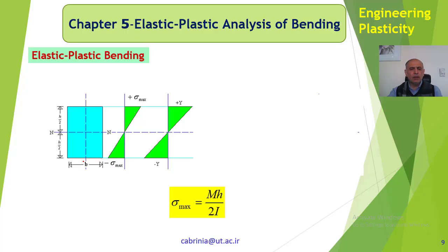Okay. Now here is the maximum also, but with a minus sign, a compressive stress. Also, as we go towards the neutral surface here, it decreases. Okay. So when we move from top to bottom, it changes from positive to negative. So there must be some point which is 0, and that is on the neutral surface. It decreases, and that decreases. They reach a common point, and in fact both of them are the same. Sigma is equal to 0 at the neutral surface, because they coincide here with each other.